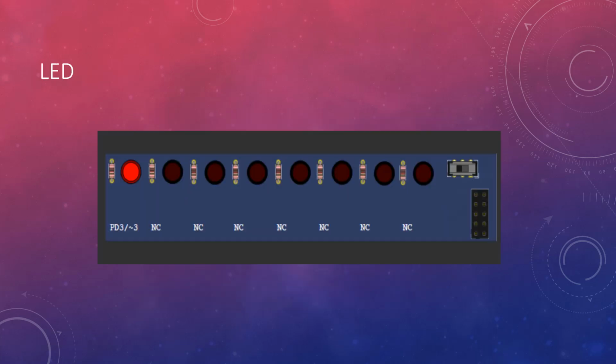So this is how the LED looks. This is a light emitting diode. It acts as a visual output device in a home automation system, and it can represent various indicators or outputs such as garden lights. It is typically connected to a digital output pin on the Arduino, using digitalWrite. You can use the digitalWrite function to toggle the LED on and off.